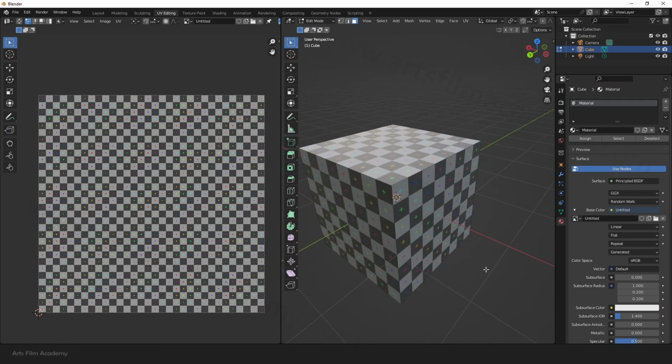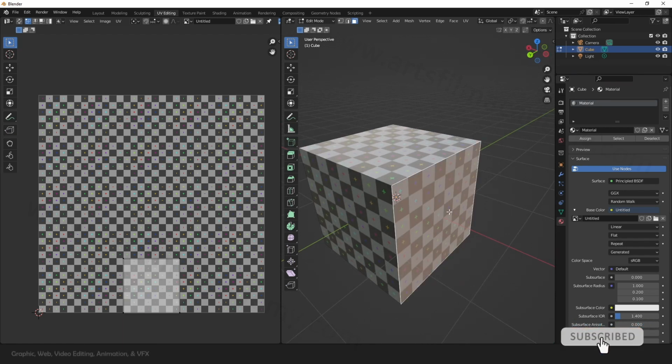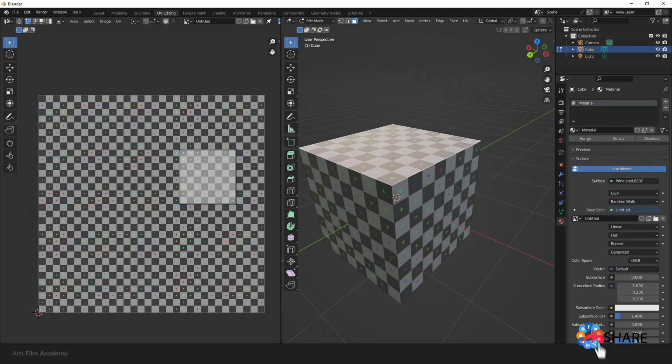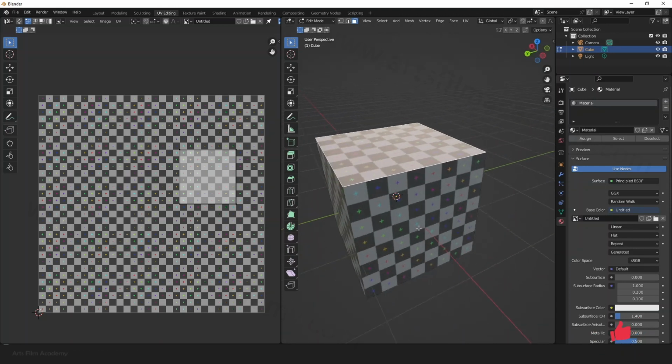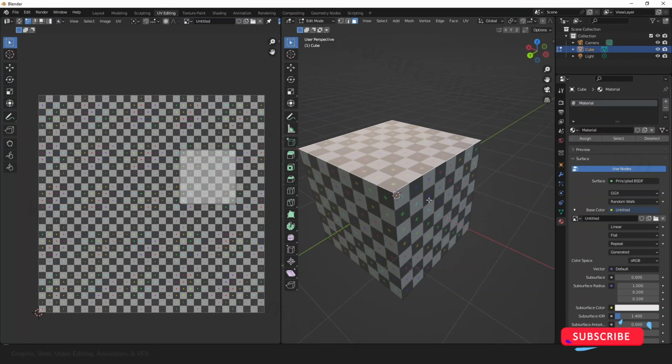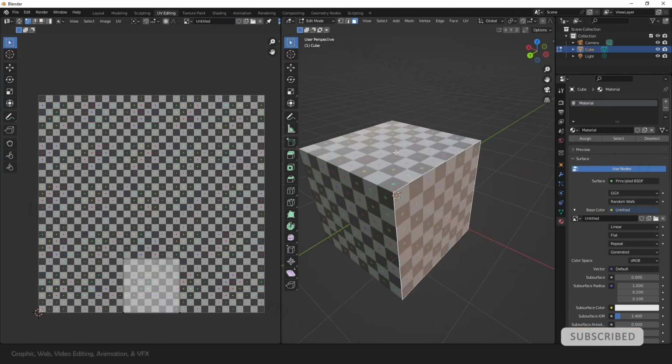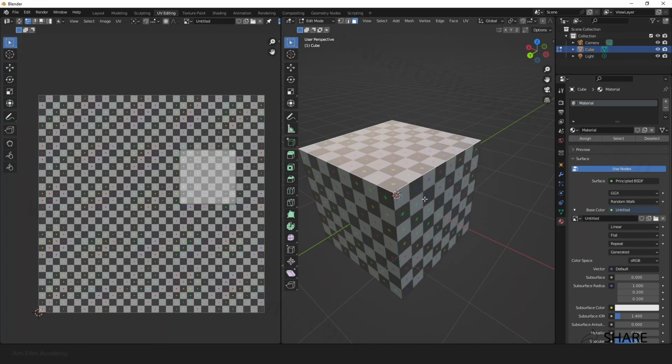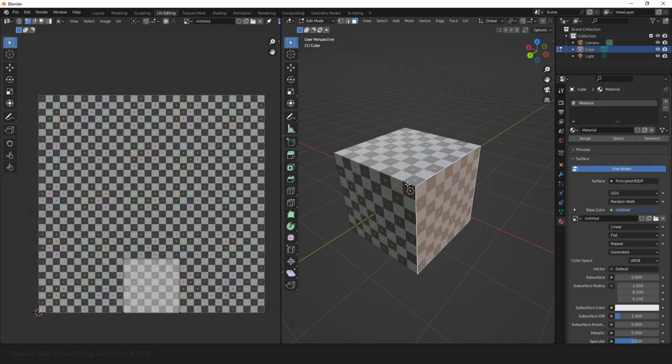Okay, now let's say I want to add a sticker or a texture from Photoshop. I want to add a logo which is wrapping from this surface and it will flow to this surface. Okay, so if I want to add a texture which is wrapping from ear to ear, these two polys need to be closer or it should be stitched, right? Let's see how to do this one.